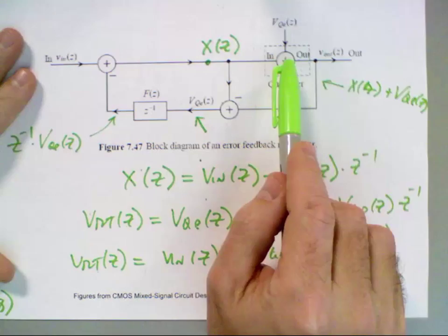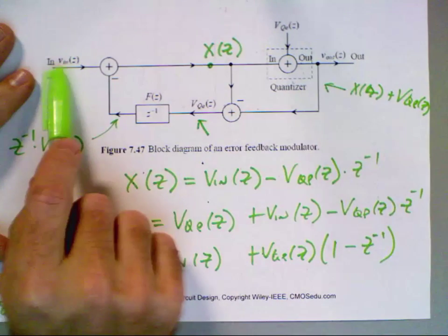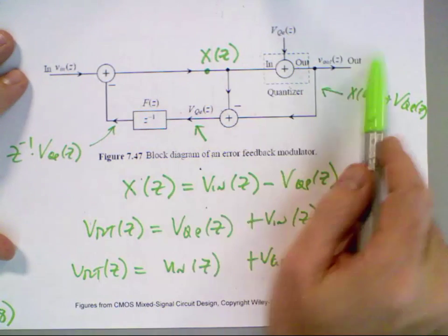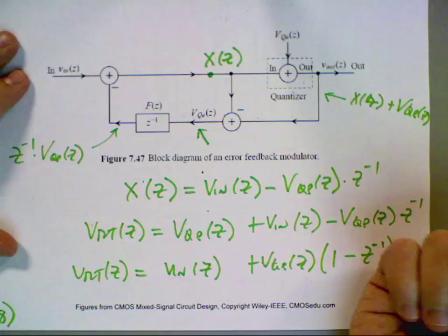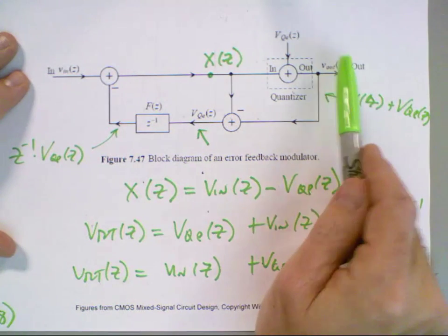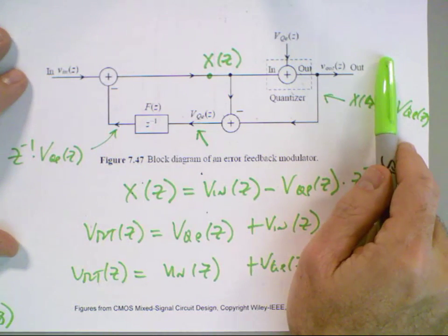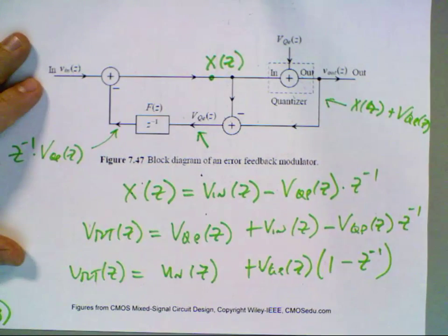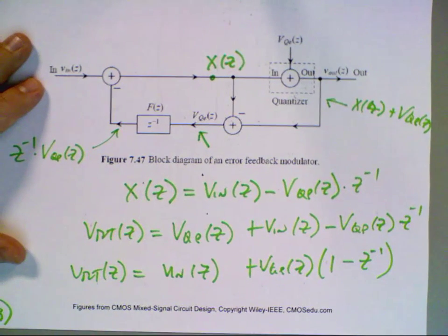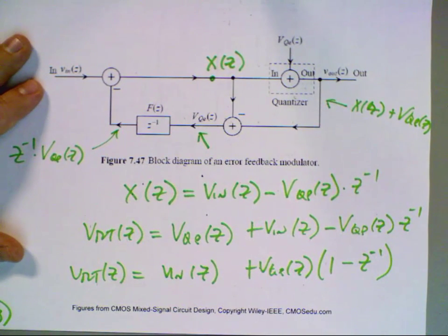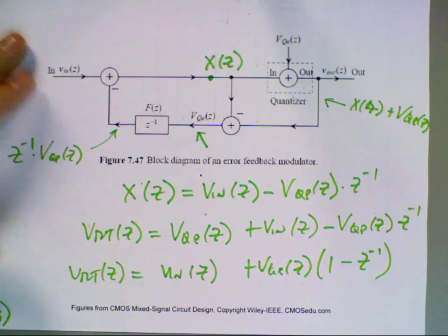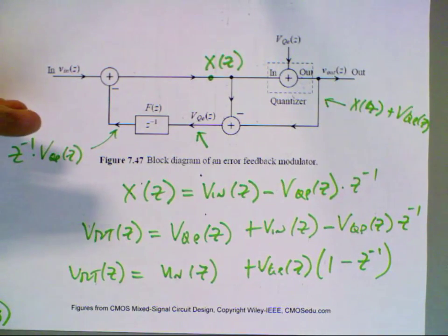Yeah, you have to clock the quantizer faster. So this word's coming in slow. This is clocked quick, so you get a real fast 1-bit output because it's oversampling. That 1-bit output then is filtered, and that gives you your analog signal, just like we're used to. And the concept of 1s and 0s and filtering at this point shouldn't be foreign. It should be very straightforward, I hope. Probably before the class, if I said you can take a 0 or a 1 and get an analog signal out of it, you would have said, no way. Now hopefully you say, oh yeah, I can do that.